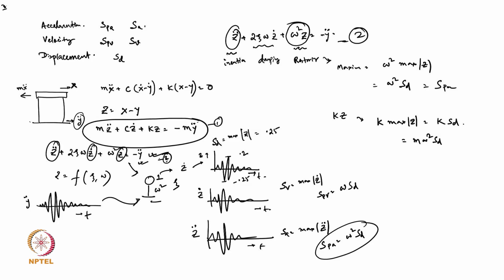There are some techniques like ambient vibration. There we can measure the frequencies. If we place an accelerometer on the building and take the readings, due to the ambient vibration we can see some peaks, and they are primarily the natural frequencies of the building.